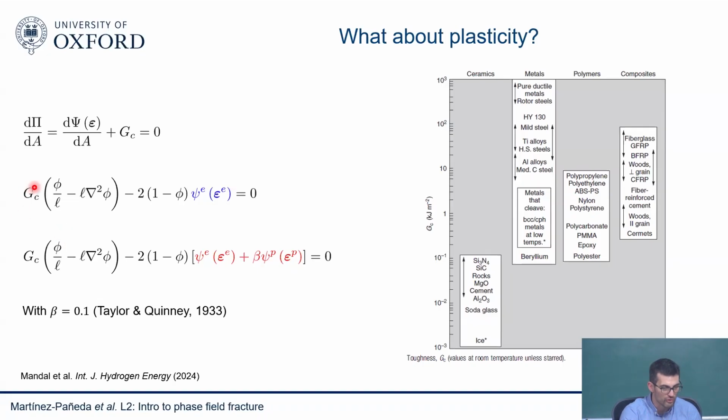What about the driving force? So you change something on the driving force. Before, we were using the stored energy, which was just the elastic energy. Remember, we plotted that bar, it was a triangle, elastic energy. Now you have a plastic energy. So what should you do here? You consider the total strain energy density, so the elastic plus a bit of the plastic energy, not only the elastic. Here in the literature, you find different people using different approaches.